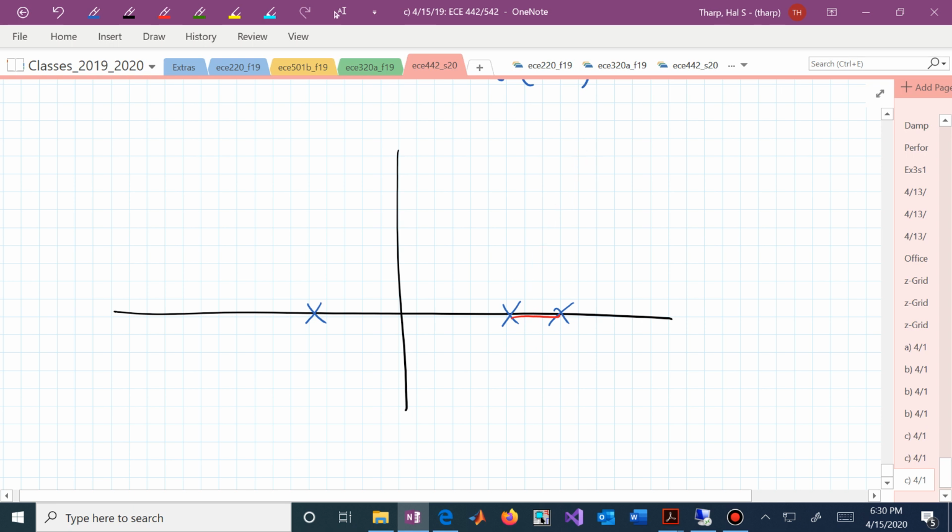If we introduced a PI controller, it forces a pole there, and it forces another pole. It gives rise to another 0, and that 0 maybe we could put there. But now, look at what that does. This was z equal to 1, so these immediately are unstable.